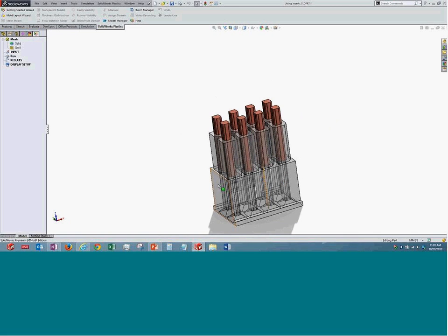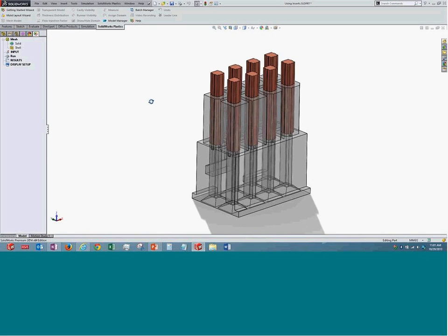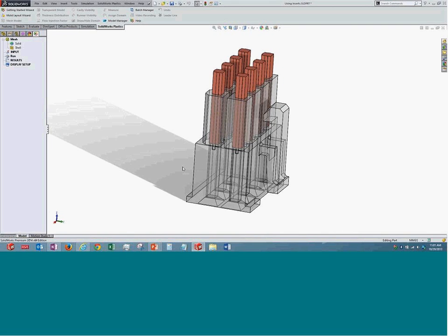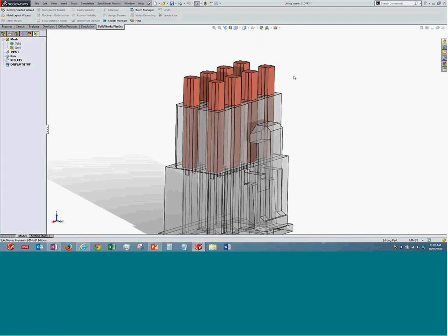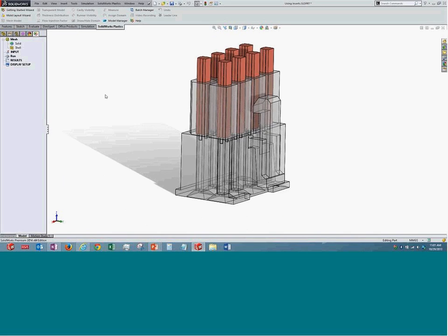Definitely, in such cases, we cannot use surface elements or shell elements. We have to use solid elements, and it would be something like this. I mentioned this, I use the manual option. At the bottom, you are seeing something called a solid mesh procedure. So set it. If we want to create the runner system, then we can use this option and the wizard will pop up. If I can neglect it, I can directly give the injection location.